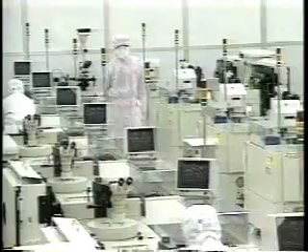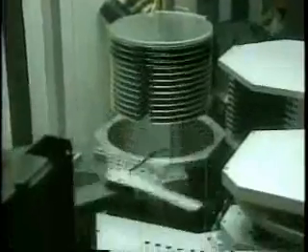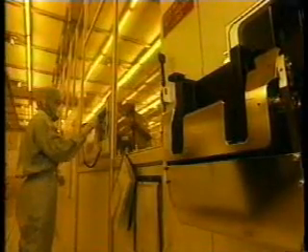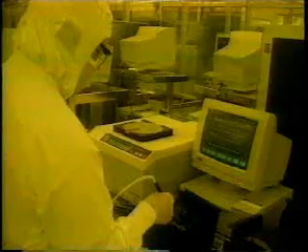One important aspect of understanding the cost of the product is to understand the cost buildup of the product as it flows through our factories. The cost of a product very early is basically just the raw materials and a low amount of labor content of a wafer as it comes into the factory, a wafer that may cost $40 for the raw substrate, going through 1 or 2 mask steps. Again, the cost we've invested at that point is relatively low. After that wafer has been through the wafer fab process and been through 20 or more mask steps, we have upwards of $500 invested in that.